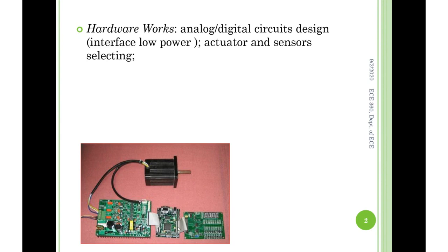They come out of the CPU, but function as general purpose IO pins, providing PWM or receiving the ADC signal, etc. The power board is going to provide the feedback, like the position signal from the motor, to the controller through a ribbon cable here. And the controller, of course, also provides something back to the power circuit.